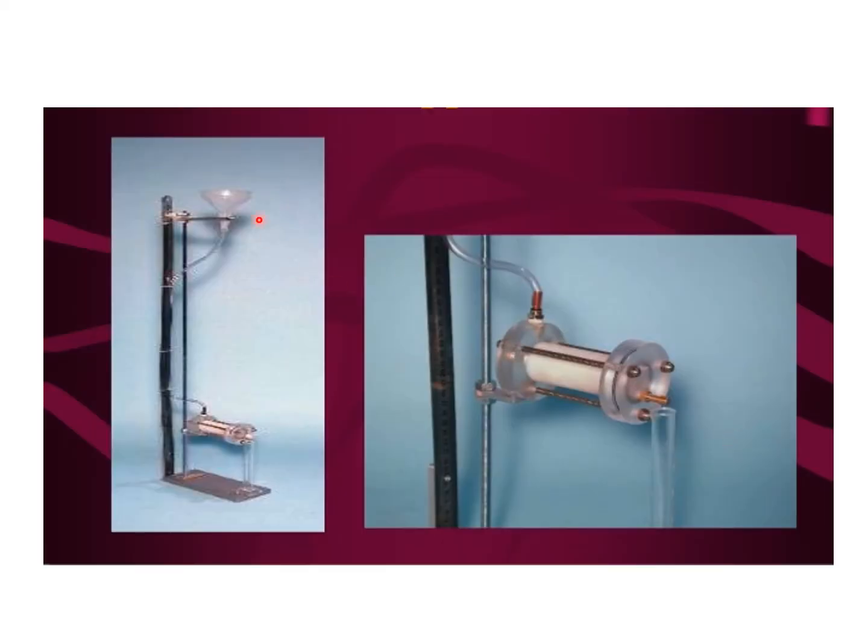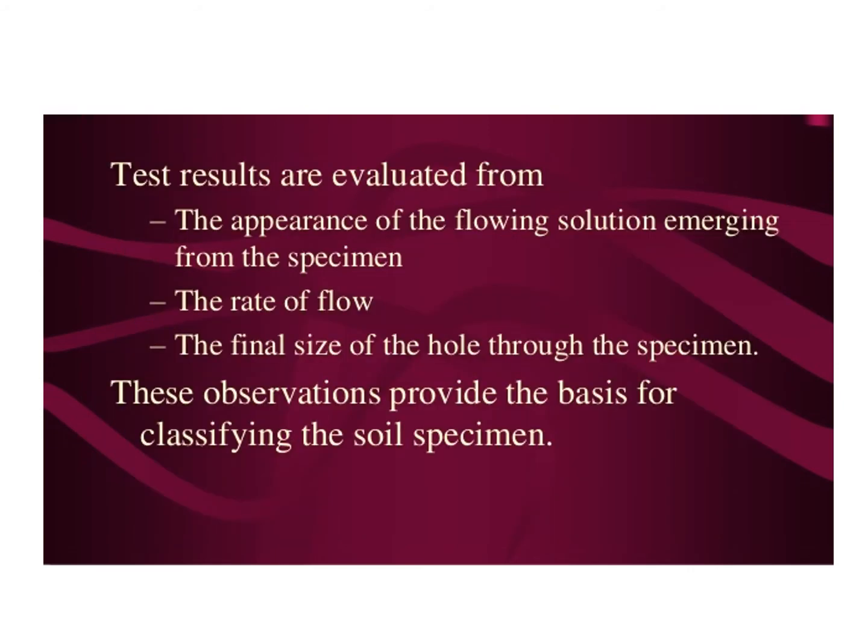So this is the real arrangement for the pinhole test. Test results are evaluated from the appearance of the flowing solution emerging from the specimen, the rate of flow, and the final size of the hole through the specimen. These observations provide the basis for classifying the soil specimen.